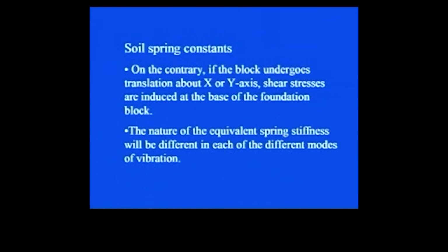With the result of that, it will undergo some oscillation, and with the consequence of this oscillation, compression will be induced at the base of the footing. On the contrary, if the block undergoes translation about the x or y axis, shear stresses are induced at the base of the foundation block. So, either the translation will be in the x or y direction.